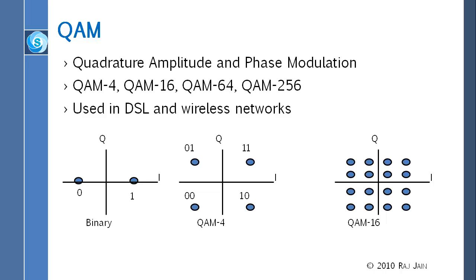And in 256, there are even more gradations, right? And then you have to be able to distinguish the phase. In this case, it is 22 degrees phase you have to distinguish. Here it is 45, 90 degree phase you have to distinguish. Here 180 degree. So this is more and more difficult, and therefore the circuit is more and more expensive.